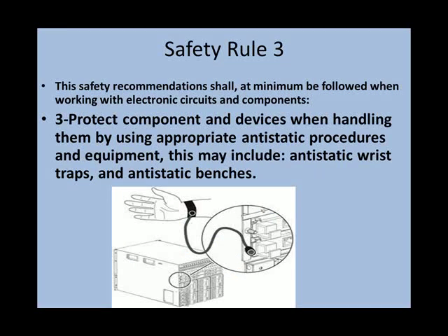Number 3, protect components and devices, because now we're dealing with components and devices that are sensitive to static voltages. So you need to use anti-static wrist straps and/or anti-static benches. Here's the case where the static energy in your body will be discharged onto the frame of the chassis of the bench and not onto the actual equipment you're working on. So always protect those components and devices by handling them properly using anti-static equipment.